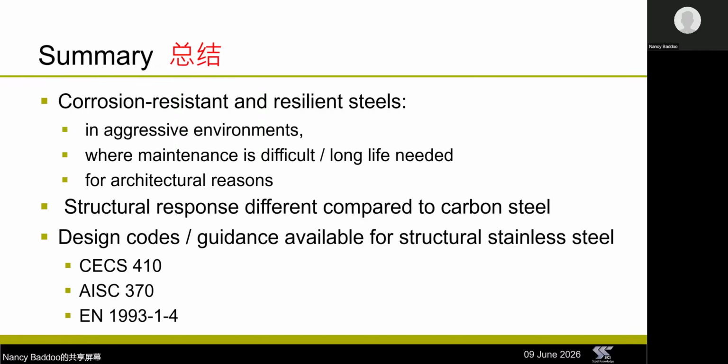In this series of talks, we've explained how the structural response differs to carbon steel in some aspects only. Sometimes you can use the same rules as for carbon steel, but when you have instability, buckling, and deflection, you should be careful to use appropriate rules for stainless steel.